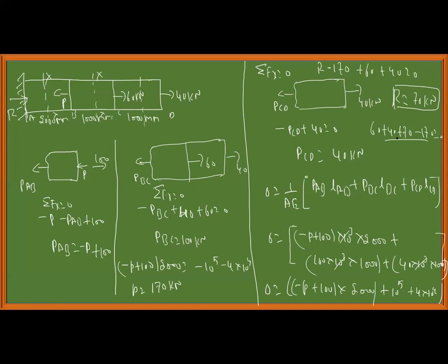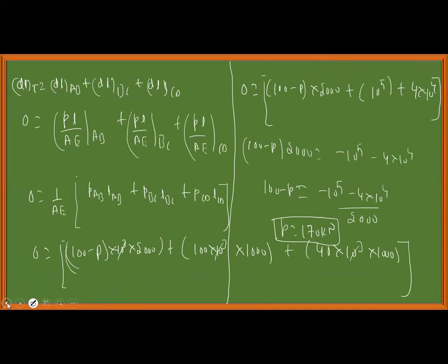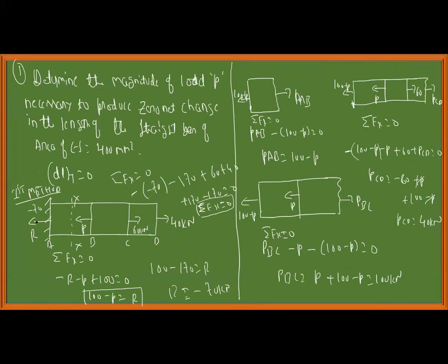If I substitute all these values and make the summation, then the total summation of forces in x direction will be equal to 0. You can also see the R value, which in this case is 70 kilonewton acting towards the positive x direction. Here also you can see it is minus 70. When we took the other reaction force, R was minus 70 kilonewton, so it is acting in the negative direction, minus 70 kilonewton. If I want to make it in the reverse sense, it is acting in this direction, minus 70. Minus of minus 70 will be positive. Okay.